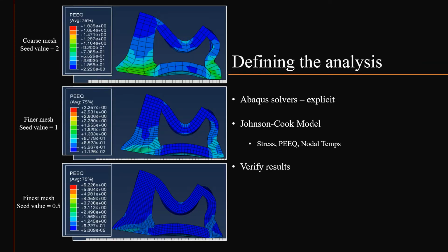Currently, there are varying views and opinions on the best way to use finite element analysis to study areas of high strain. Due to a shear band's short time frame of initiation and large impacts, numerical analyses can vary widely in terms of accuracy. 2 different numerical methods can be used to model shear bands: implicit and explicit. Originally, I had wanted to run both an explicit and implicit fully coupled solution and compare the results. However, only an explicit analysis was performed due to time constraints and computational limitations associated with contact and element distortion.